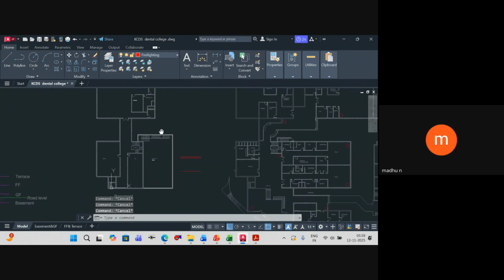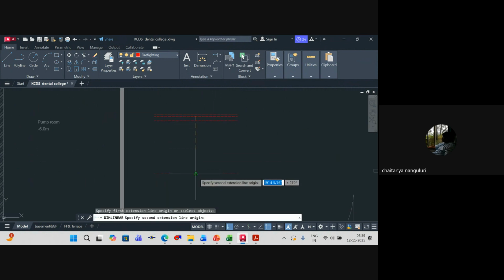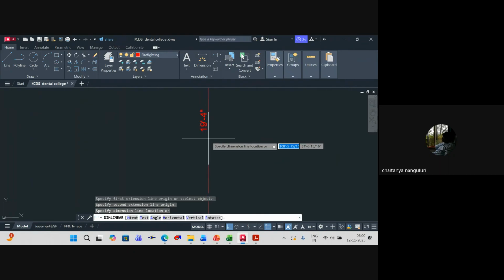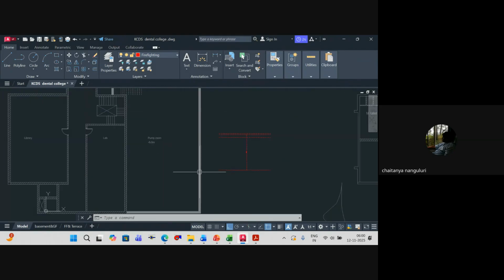Of course, wherever my pumps are exactly, there will not be a beam. So our effective depth availability will obviously be this one. If you see this, we have a value of 19.4. But again, it's mandatory for us to have a positive suction. So this is the floor level of my pump room. Don't you think my tank should be at a certain raised level? Yes. So obviously my tank should be at some raised level, so that at least will take around 600 mm, offset 2 feet.